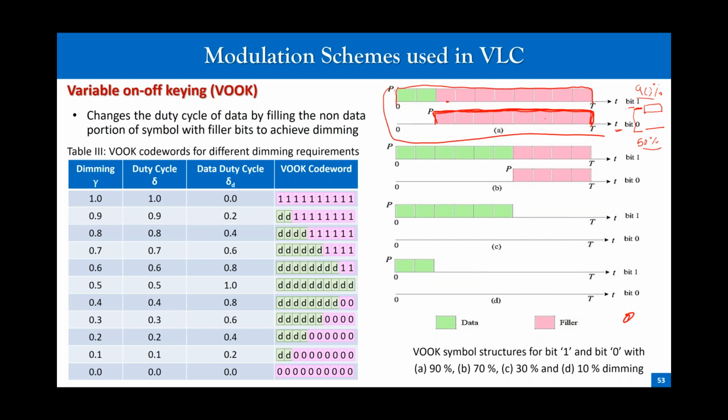Now there is one downside of this approach, which is the distance between the two signals. So normally for error performance, we calculate the distance between the two signals. The distance between the two signals only depends upon the green part, because the green part is the only part that is different. The purple part is present in both the signals. Okay, so the distance between the two signals will reduce. So that's the downside of it.